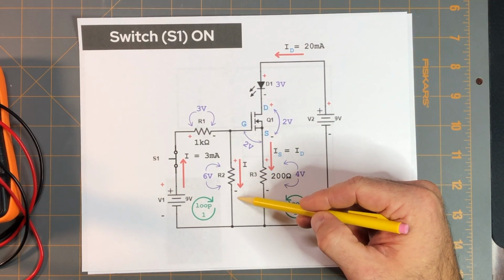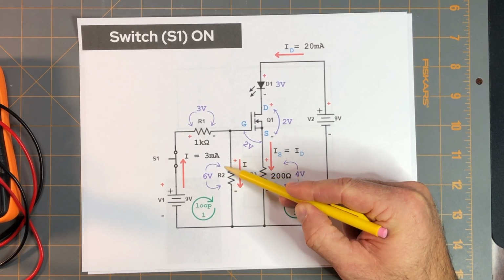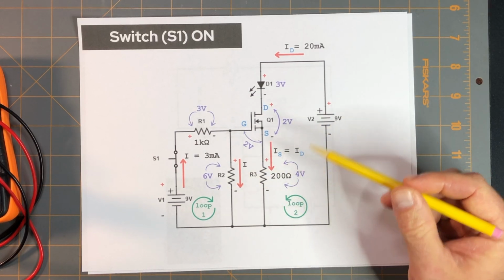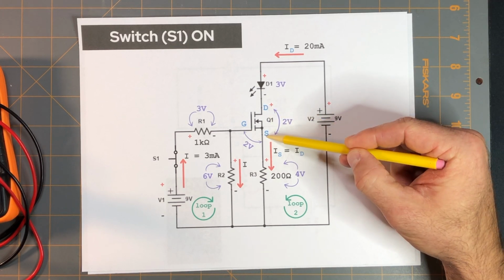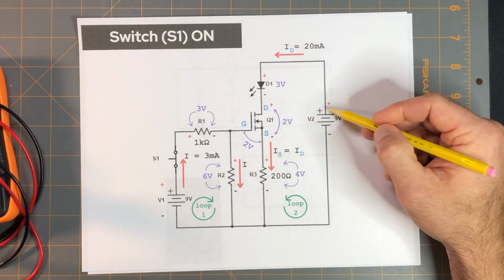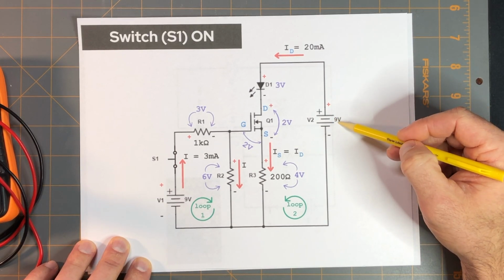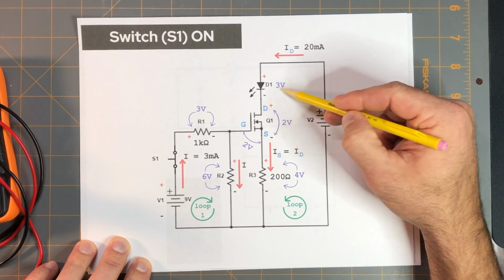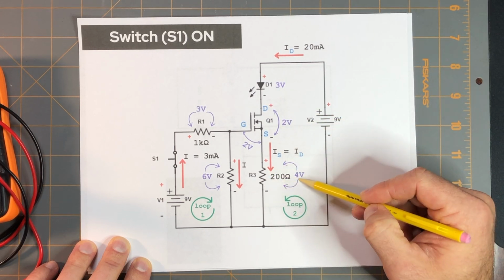Although I didn't put that value in here, that's the value of the resistor R2 that we were able to figure out in that example problem. And then again, we were asked to find what the drain to source voltage was across the MOSFET. All we would need to do there is again use Kirchhoff's voltage law. We know the source voltage is 9 volts. We were given that the voltage drop across the diode or the LED was 3 volts, and we found that the voltage drop across resistor R3 was 4 volts.